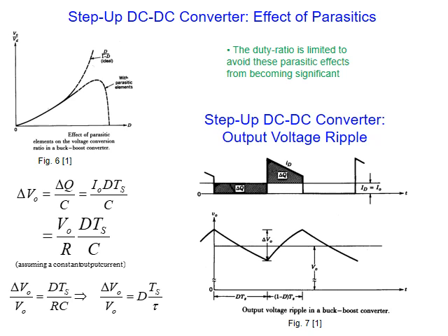One more issue here is the ripple voltage. Ripple in voltage is exactly similar to the boost converter. Here we have charge, here we have discharge. This is the current of the diode. When the switch is on, it's zero current, and when the switch is off, the same current of the switch will flow from the input through the diode.